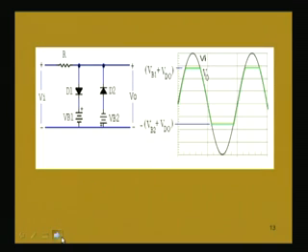So, now we can draw this output voltage waveform versus input voltage waveform. Input is this black one, Vi, and if we now find out and plot the V naught, this is 0 starting with this. So, when the input voltage half cycle is positive and input voltage is less than VB1 plus VD naught, the diode does not conduct. When the diode does not conduct, then this voltage is the same as the input voltage, because there is no conduction of current, there is no drop here. This point and this point do not have a difference in potential.